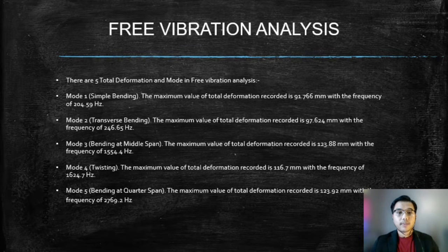The maximum value of total deformation recorded is 116.7 mm with a frequency of 1624.7 Hz. Mode 5, bending at quarter span. The maximum value of total deformation recorded is 123.92 mm with a frequency of 2769.2 Hz.